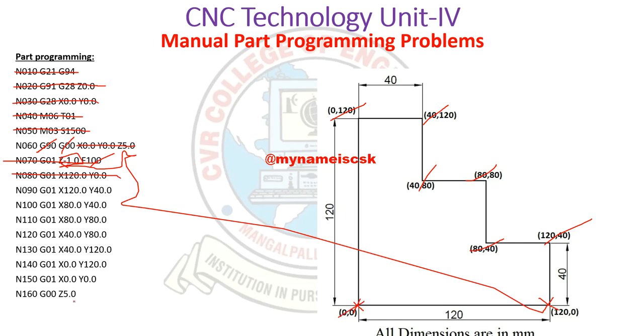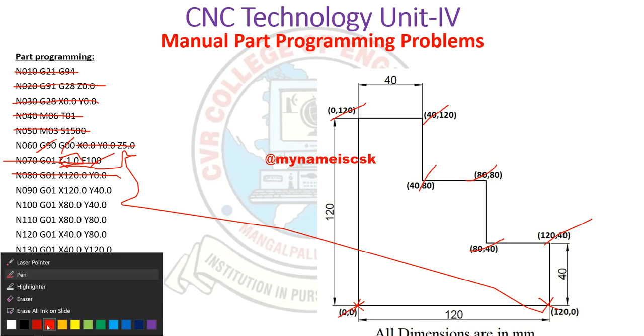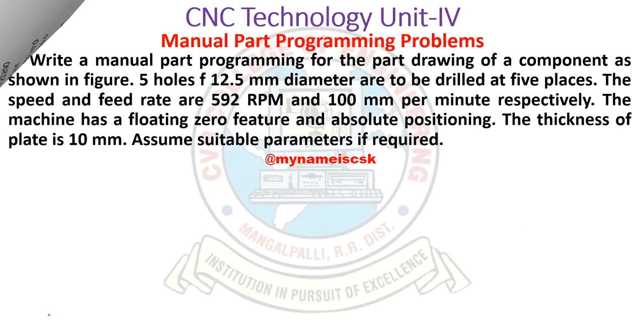Then for Z we are giving the vertical height as 0, so that it is not touching the workpiece. Next it will go to the home position, X0 Y0. Generally we will consider X minus, Y minus 5 as the home position. And next the spindle is stopped. Next M30, which is nothing but program stop and tape rewind. So this is the program.